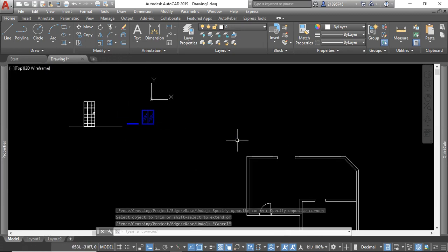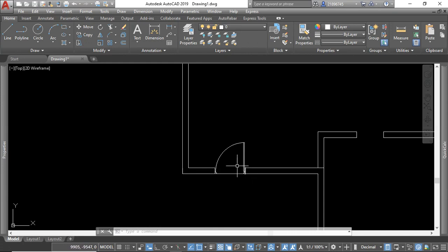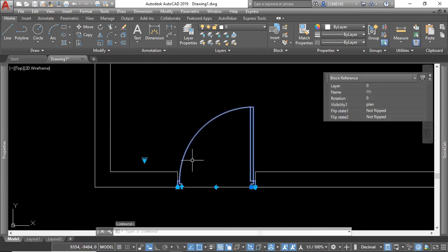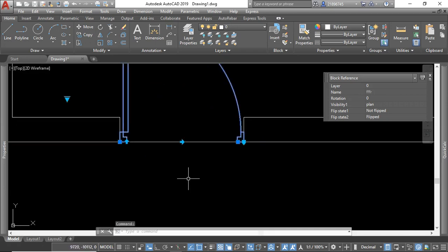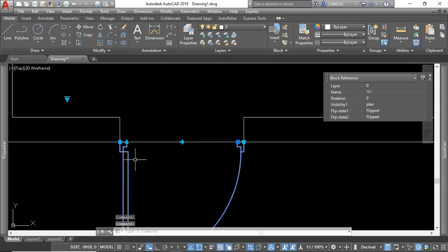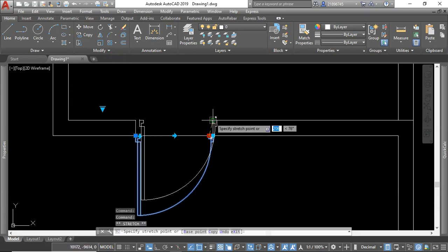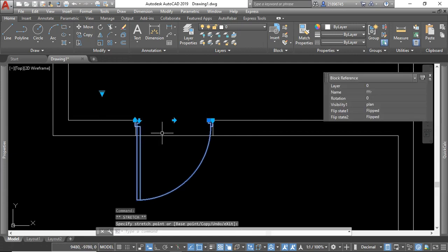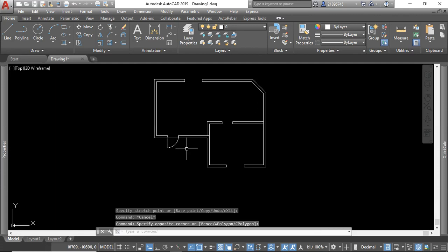So the other place I can use the window, but now you know, I wanted to show you something here, because this door has so many things that you can change. For example, if I click here, it will change the direction, or if I click here, it will change the orientation, maybe to open to the outside. So just come here, sorry, then I do like that, and then my door is opening to the outside. For now, let's just keep it like that.